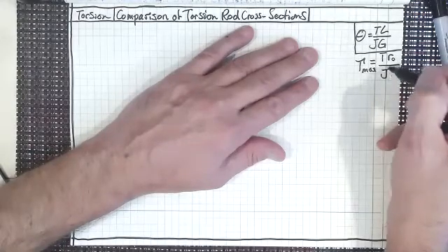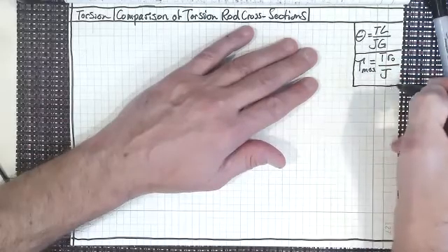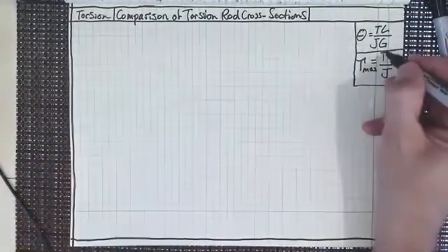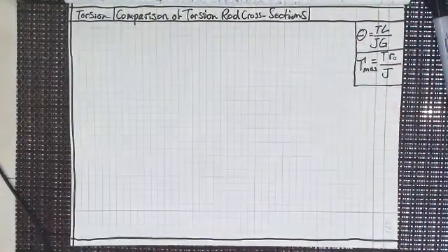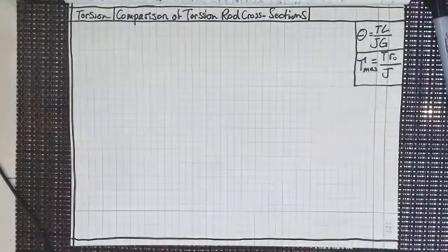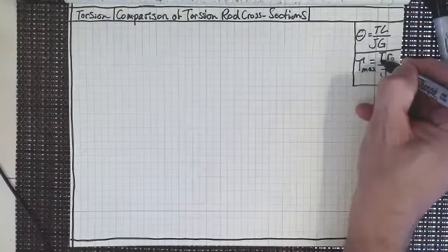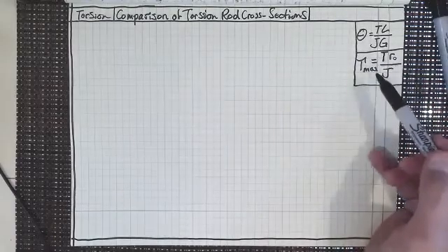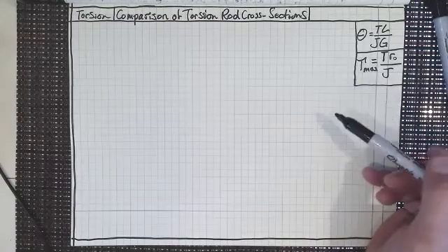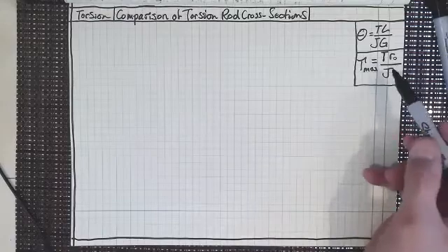Always remember that. Does it fracture on the outside in torsion first, or does it fracture on the inside in torsion first? And of course, at the very center of a torsion rod, there is no stress. So in torsion, things always fail from the outside in. All right? They fail from the outside in. And that's the same in flexure. All right, let's